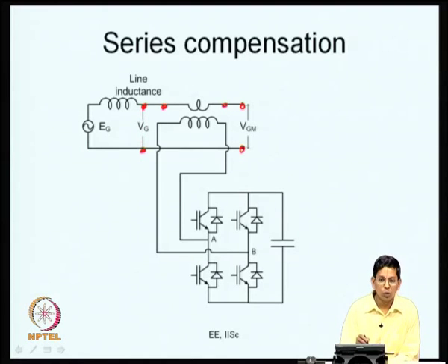Now, let us say you have a voltage swell on the other hand. In series with it you inject a voltage which is out of phase, and therefore the amplitude at VGM will be less than Vg, and you can get what you want at 230 volts or so. So, voltage sag or voltage swell can really be handled like that. Then what do you want to do with distortion? Let us say you have some sinusoid plus harmonics here. What you try doing is you inject those harmonics in phase opposition. So, you may not have that kind of distortion at VGM, and VGM is of acceptable quality.